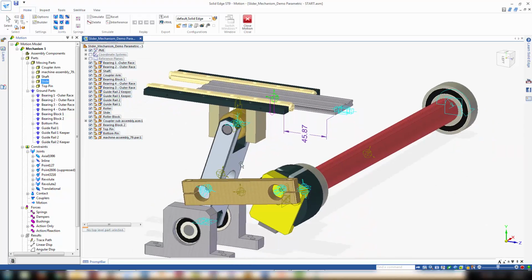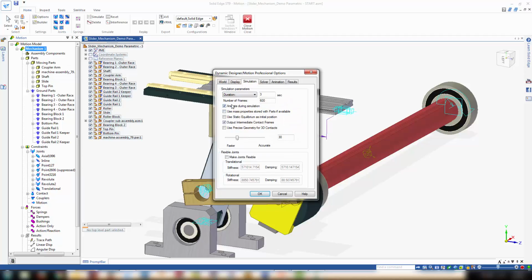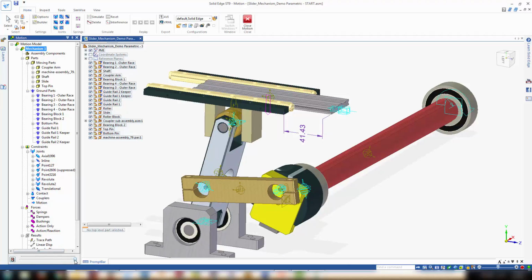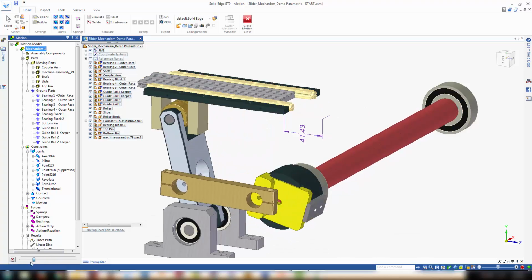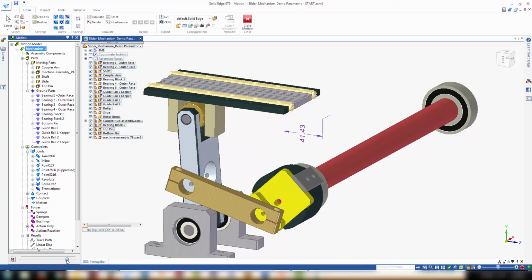Okay. And another thing I can do is turn off the animation while it's solving. So if I'm doing successive runs, making a lot of changes to it and rerunning it several times, I can turn the animation off so it only crunches the math. I still have access to the animation after it's finished, but watch down here when I simulate how quickly the slider bar will move across. There, I've just completed 3 seconds of data, but I still have access to my animation. So it just doesn't show the animation initially.